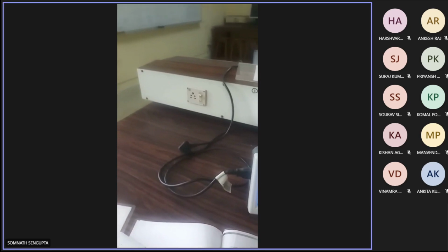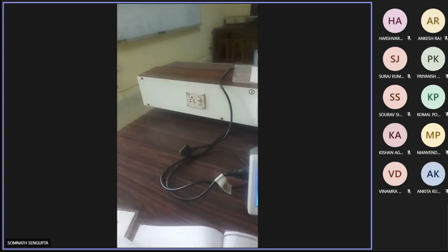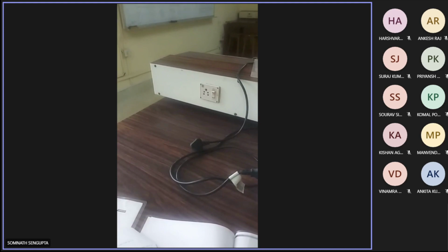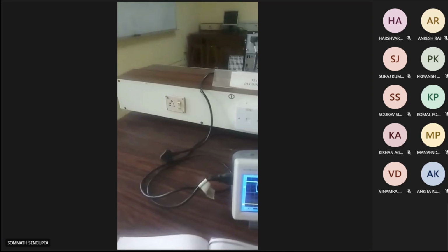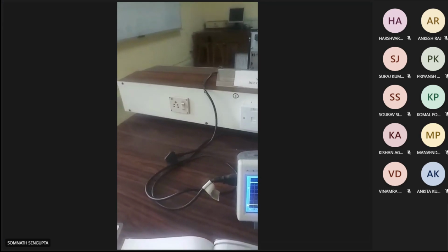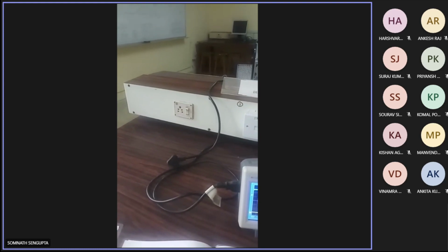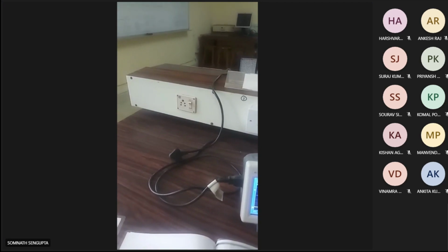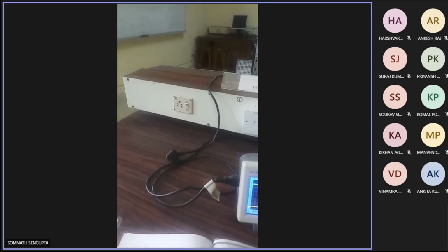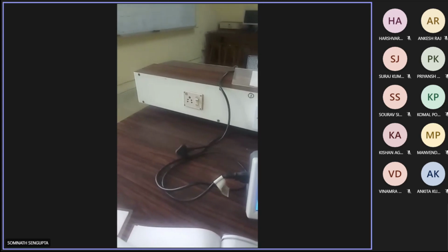So once the clock recovery is completed, you apply that recovered clock signal to a D flip-flop, and the Manchester coded data we apply to the D flip-flop as well. Then you will see that the D flip-flop produces your Manchester decoded data.